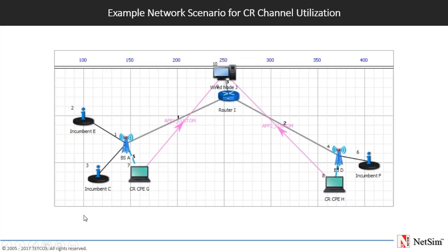In this file you can initialize Matlab, then execute various Matlab commands through a .m file. You can get variables and send variables between Matlab and NetSim, and finally you can shut down the Matlab process. What we will do now is show you how this is used to plot the frequency utilization in a cognitive radio network at runtime.